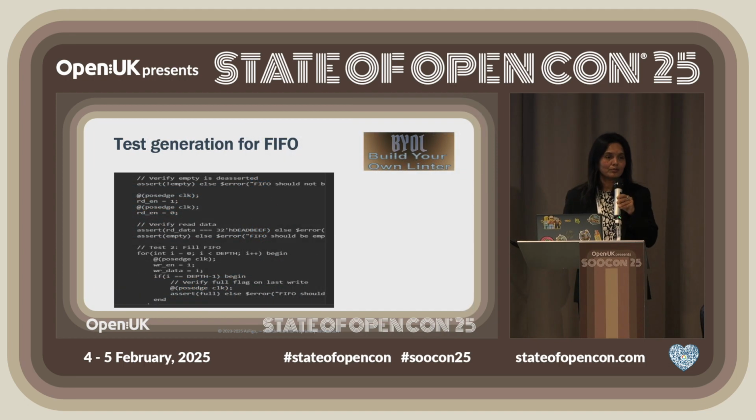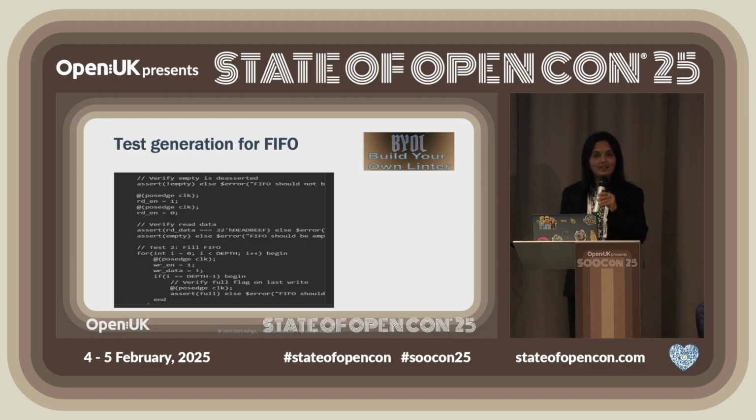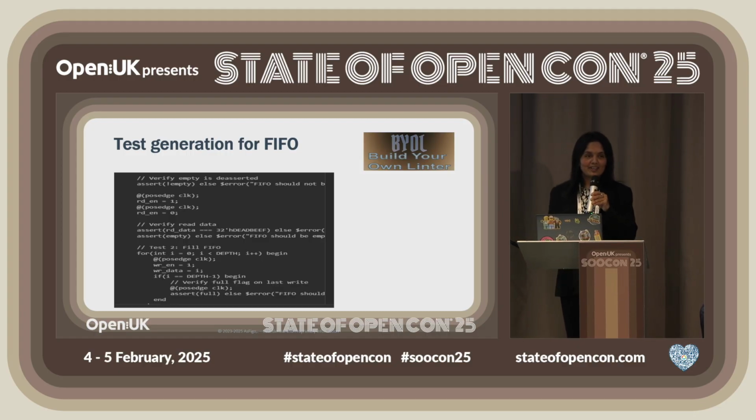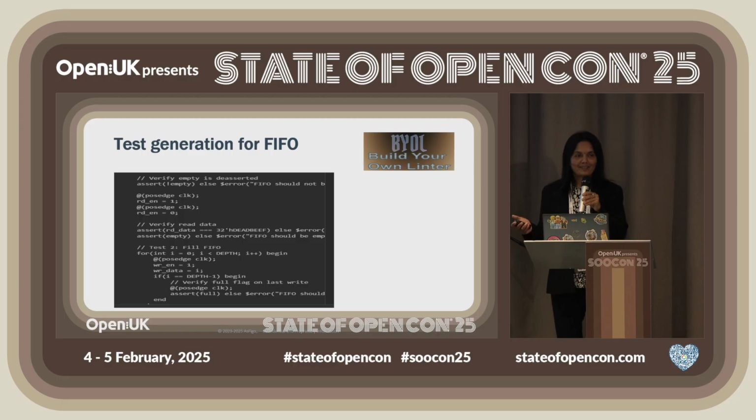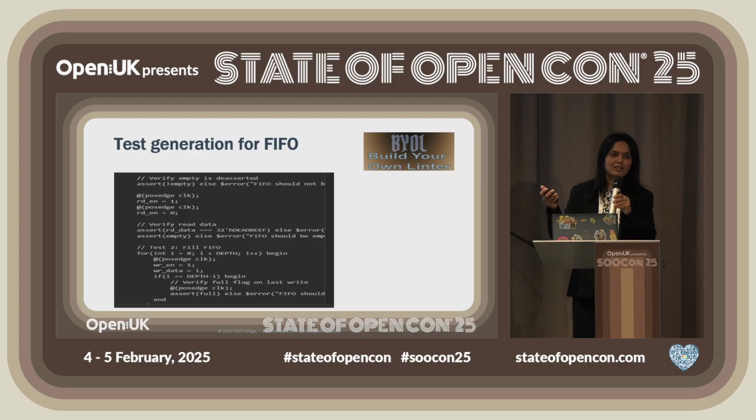All right, so now the test bench is there. Then I asked, can you give me a test case? It is for a FIFO, and I want to check the full and empty conditions. FIFO full happens when you keep on writing and see how many writes it takes, and whether the condition matters or what happens. So I asked it to write a test case, and it has done a pretty good, decent job.